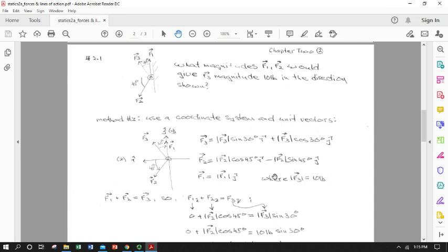So one thing you're going to find in statics problems is you will end up trying to get the same number of equations as unknowns, and you'll use your equations of equilibrium and definitions of moment and anything else you know about the problem to write a relationship, and then you'll list out all your variables, the things you don't know. And you want to have a situation where the number of knowns and unknowns is equal, because then you get one exact solution. So you want the same number of equations as unknowns. So I just set up some relationships that I know. I just used geometry to write portions of my vectors that I know are pointing in given directions.